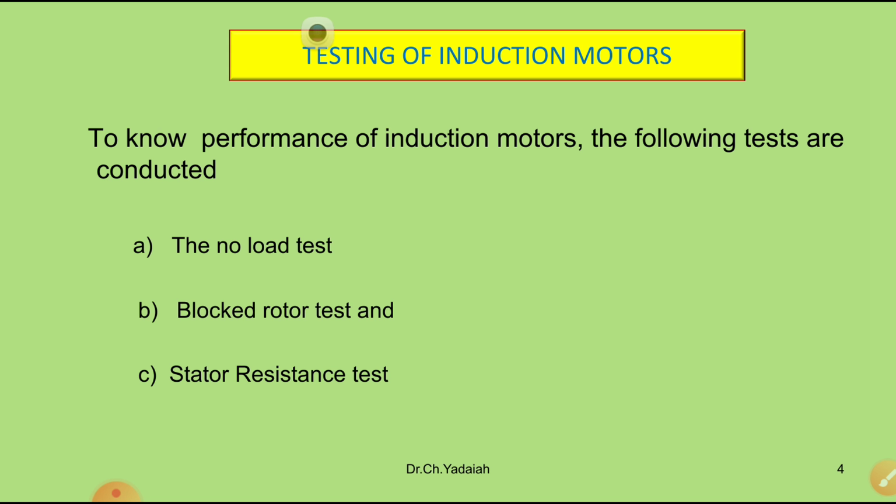Similarly, under standstill condition, our three-phase induction motor looks and works as a three-phase transformer. Here we are going to conduct the test on a three-phase induction motor with the help of some meters: voltmeters, ammeters, wattmeters. To control this, we require one auto transformer. So, we will see these tests one by one in detail.